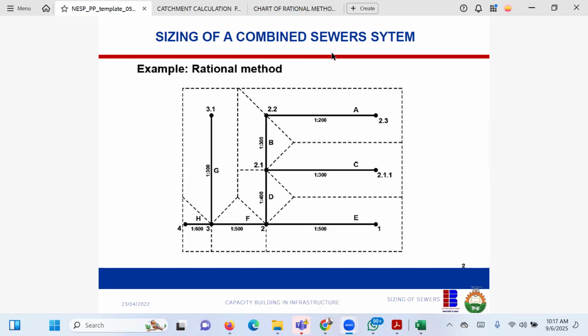That's just the point. So this main pipe might probably be 300 mm, 450 mm, or 250 mm. The minimum is 150 mm. And then when it is getting towards the treatment plant, of course, it will become maybe 600, 500, or whatever, depending on the discharge, depending on the population equivalent.